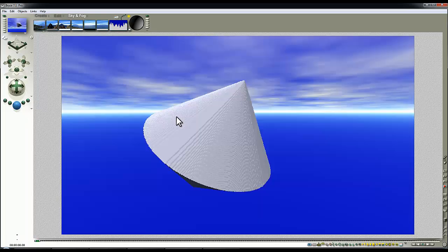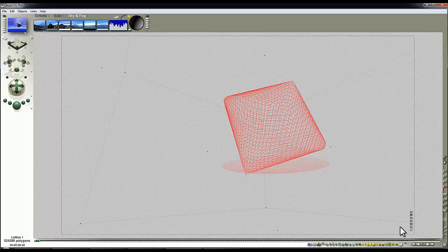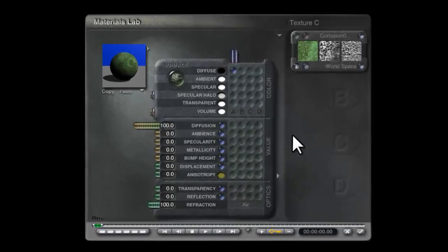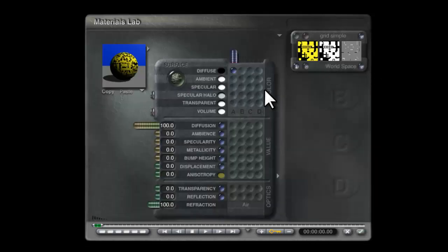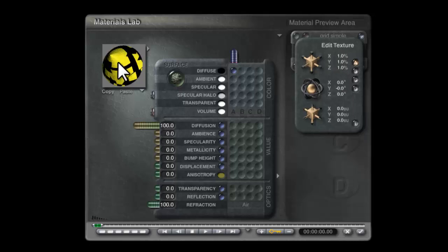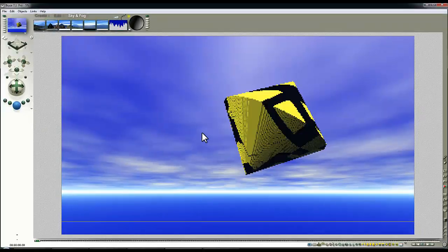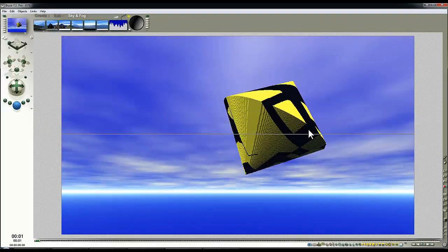So we should be able to get some kind of handle on what's happening to the material as it goes around this object. The material I'm going to use, I'll just put a blob in the diffuse channel. We're only dealing with the diffuse channel here. I'm going to hold the shift key down to go in the library, go to where basic is, use this grid simple because it's quite distinctive. World space map is good. If I use actual selection, I can see what I'm getting on the shape, which would be great. And then I'm going to lower this value here, the scaling value, so we've got a fairly distinct pattern that should give us some idea about what's going off. So I'll just go out of that, have a quick render. So you can see the important thing is that the pattern's wrapping around this join point where the lattice is mirrored. So here we go, we've got it on the top.